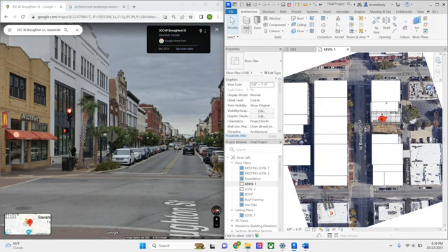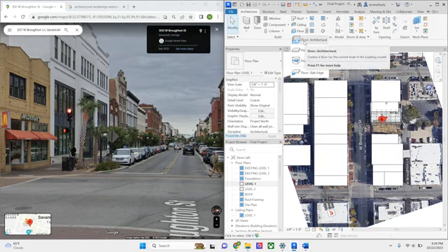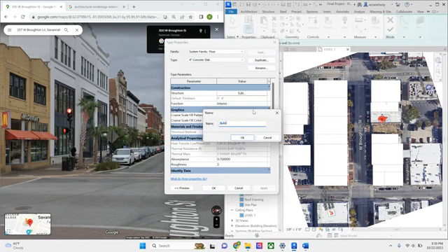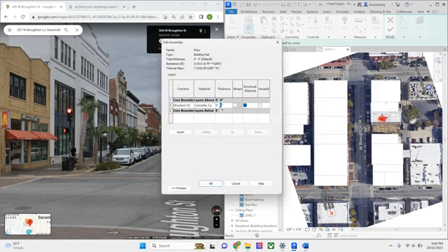So let's start there. I like to do that out of floor, which I know sounds weird, but remember I said you fake it till you make it. We're going to do floor, architectural. I'm going to create a building pad, which I might cut into and create sidewalk, and we'll talk about all of that in a second. But first, what I like to do is create the building pad. Then I'll edit. I'm going to make it 6 inches